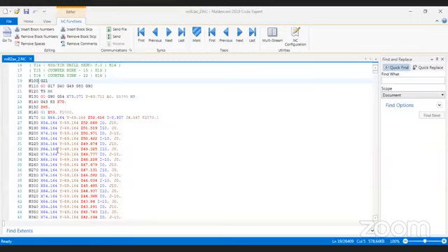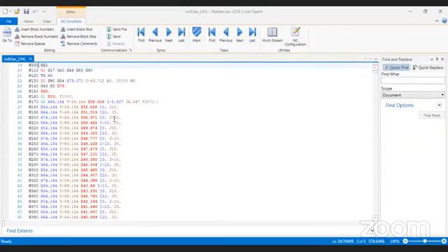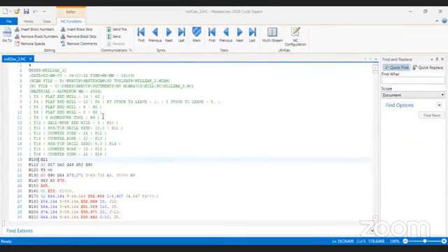So that will be the final post processing details, which we need to give to a specific machine, and it will mill accordingly. So here is the code we can see right now, which has been generated by Mastercam. This file can also be opened in Notepad. So if you want to use some specific details, you can edit it manually also.